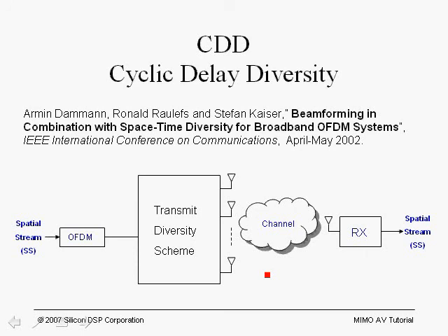And in 802.11n, the system can use the same acquisition that is used in 802.11a in order to be compatible with legacy systems. At the same time, we need to use multiple transmit chains, so we're not going to shut off the extra transmit chains during the initial acquisition.